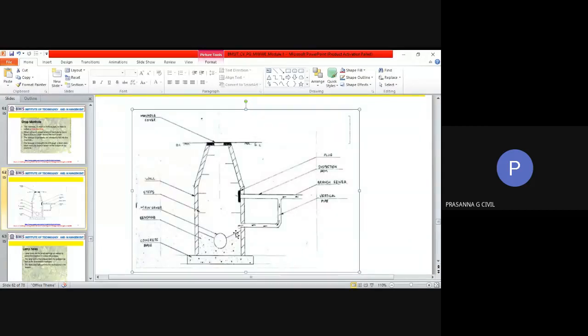The plug is provided where the branch sewer is intersecting with the shaft of the manhole. That section of the arm we can call the inspection arm, because sometimes sewage flow may cause some block here or something like that. By removing the plug and cleaning from here, we will be able to dislocate any solids that are getting stuck there. So that is your second one.